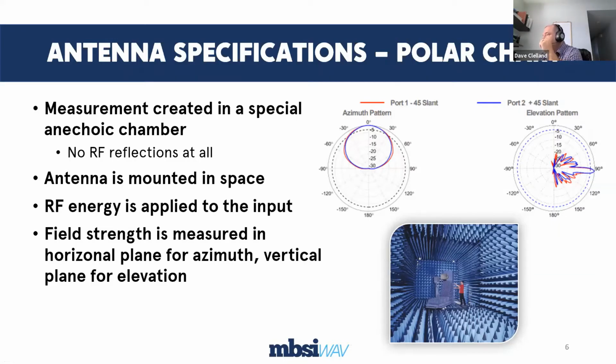We are down a little bit more, right around the 30, 5, 10, 15 dB at the positive 45 degree polarity now out of this antenna. It's got a little bit more attenuation. So we see we're down a couple more dB than that. So the antennas aren't exactly the same. The left and the right slant in this particular case have some differences.